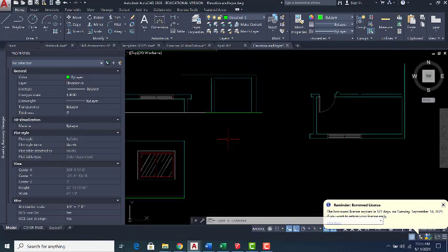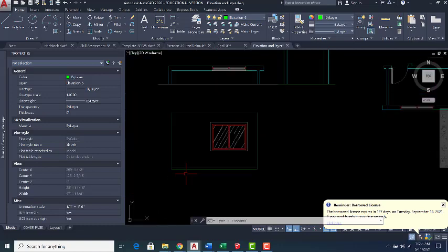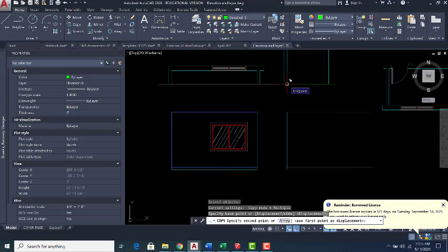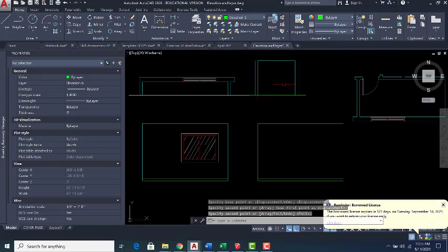I have nothing here to show, just one rectangle, but sometimes you have to show it because, for example, you want to add a picture frame there, you want to decorate that wall. So even if it's an empty wall, we sometimes have to show it. Here, I'm not wasting my time. Remember, guys, it's the same room, the same floor height, the same ceiling height, the same baseboard. I would copy this part, select one side of it, accept my selection, grab the interior side of this wall, and move it all the way to the interior side of my new elevation.